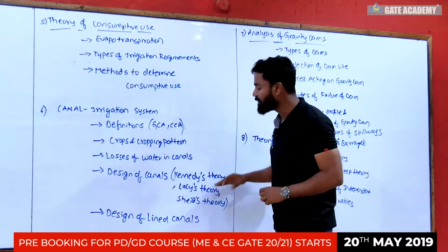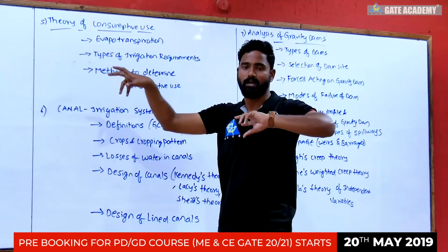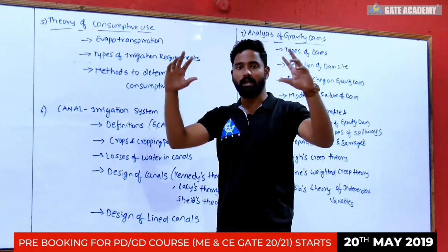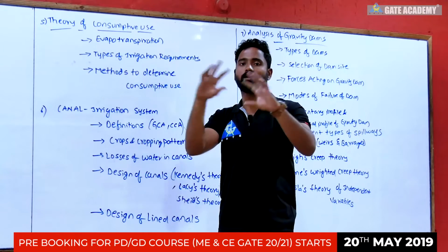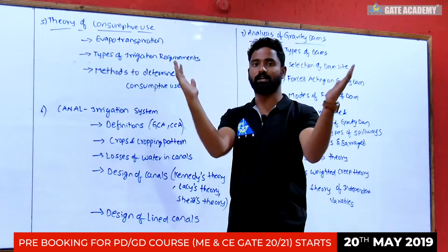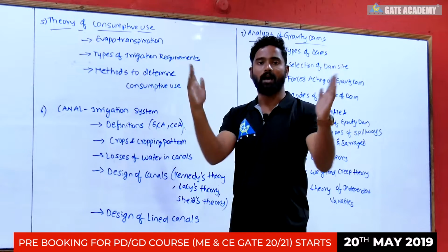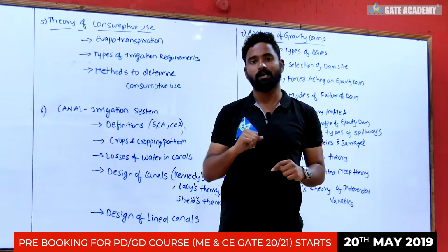And in Lacey's theory, the idea is there will be initial regime, true regime and final regime. What is initial regime, what is final regime? A canal gets adjusted. In initial regime, side slopes get adjusted, and in final regime, the bed slope gets adjusted.